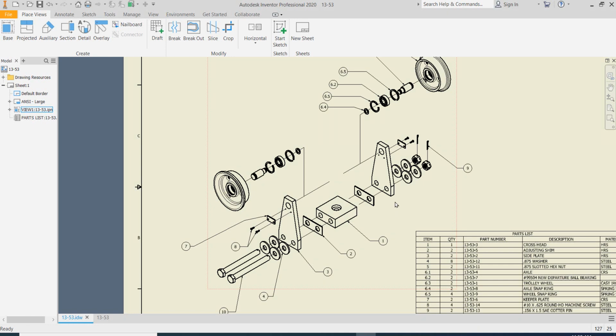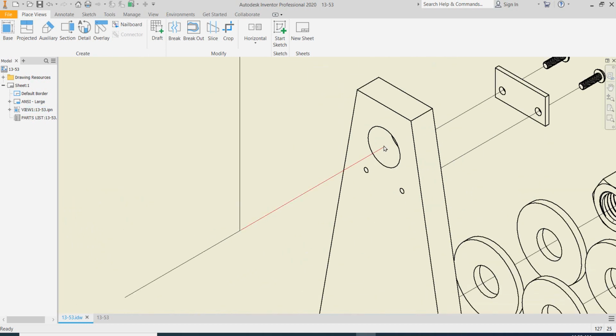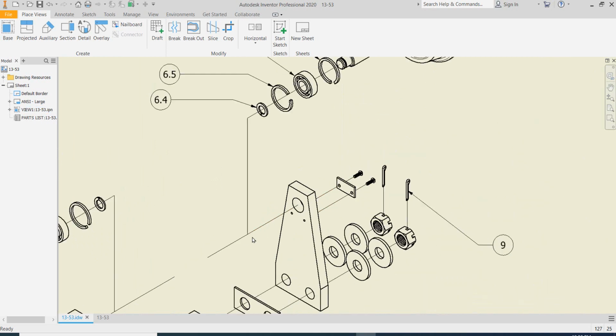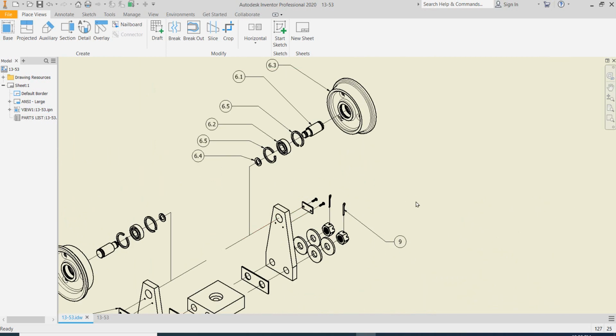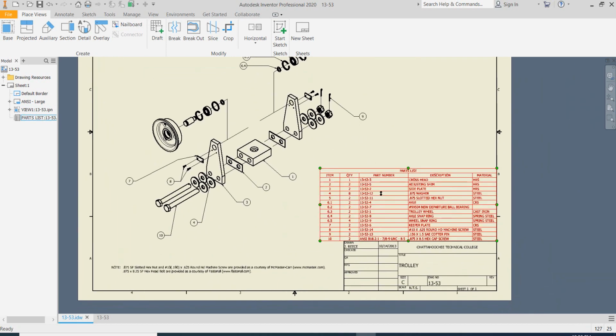And did the same thing down here. I would grab all of these items, move them at one time back this distance, and then move back and do the same thing over again. It cuts down on the number of trails that you've got. And then sometimes if it just looks wonky, I will turn off the trails and just draw my own with a sketch. You have to project geometry, but you can draw from center of circles back to intersections and things like that. So it's whatever looks great. All right, so now the parts list.